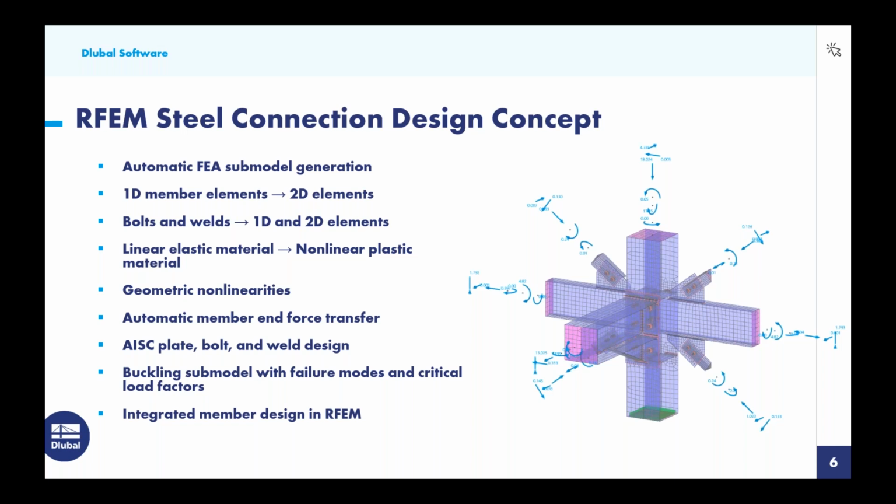And what I mean by this are topics called surface contacts, where essentially if we have two plates modeled together, they can fail in tension so that we have our bolts take over those forces, but in compression, we should see full force transfer. Some of the members, such as those spoke members that are modeled around our bolt elements, will also have nonlinearities applied.